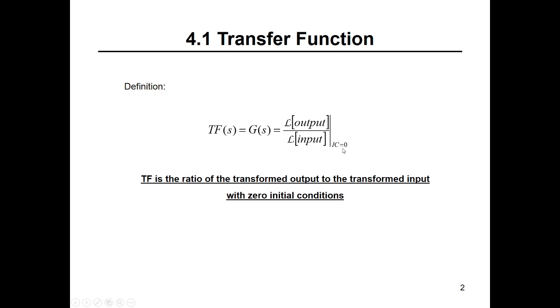You need to remember two things about the transfer function. It's always in the Laplace domain, not in the time domain. And it's always assumed the initial conditions are zero, no initial conditions in the transfer function.